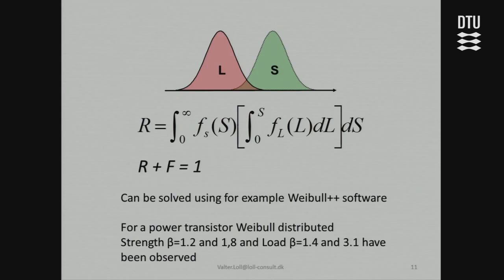You can see here that now we are looking into fatigue and degradation. So the designer must, at time 0, make sure that there is a margin between the load and the strength curve. And if we want to test for that margin, we can use the HALT test to find out when it fails.